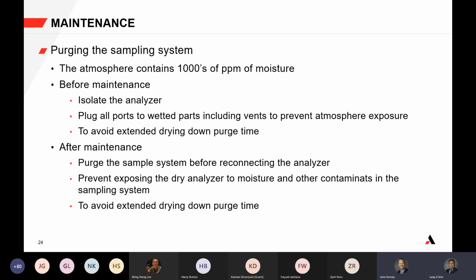Yeah, with regards to how good they are, I think it would really depend on the quality of the bottle and the way the bottle is stored. When I mean the quality of the bottle, as mentioned, internal surface area matters. So it depends on whether it has an electropolished surface, which is the highest quality bottle, or a bottle that is not electropolished.